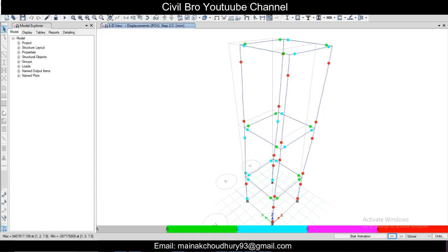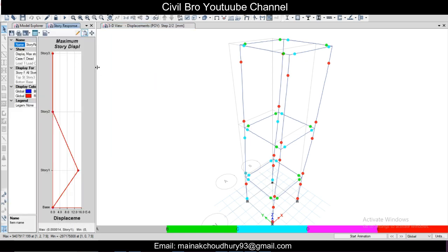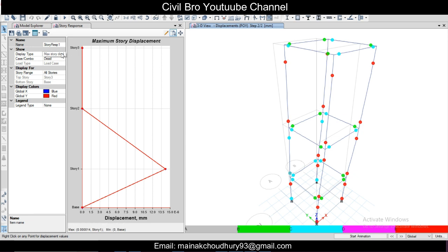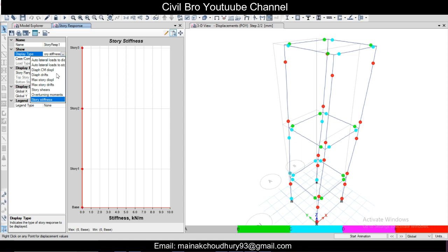So let's see the story response plot and display the story response plots. You can see the maximum story displacement in mm, and the maximum displacement is more than 13.5, and this is the story response 1. I can also see the maximum story drifts at around 7.2, and this story stiffness. So all this we can see here.